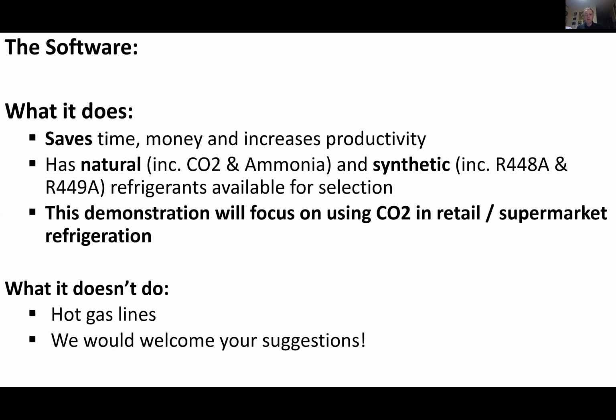What it doesn't do, we don't do hot gas lines. The reason is it's been predominantly used in the UK. Hot gas defrost isn't commonplace within the UK. Medium temperature applications, they use an off-cycle defrost typically in a supermarket. Low temperature systems use electric heaters within the coil bank within the display case.